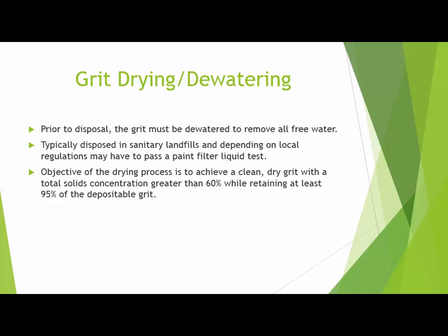Dewatering is important due to a lot of the environmental regulations being placed, especially at our sanitary landfills. Once the grit is dewatered from all free water around the particles, it must be able to pass a paint filter liquid test. Did a little bit of reading about this.